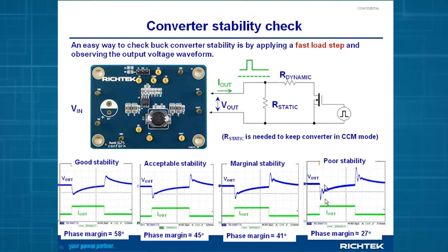And when you see this kind of waveform with a lot of ringing in the step load response, you know you have a problem. The phase margin will not be sufficient and you have to make some modifications to your application.